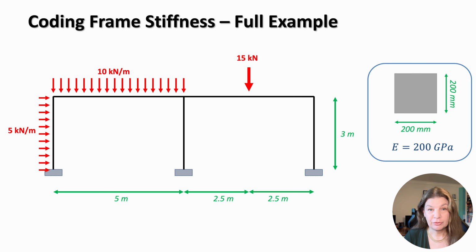The key point about this frame is that it is statically indeterminate. Equilibrium alone is not enough to determine the internal forces. We need compatibility. In fact, this is a 6-fold indeterminate structure, meaning that there are 6 additional relationships required beyond simple equilibrium. It's exactly the type of problem where the stiffness method is most effective, because it naturally incorporates both equilibrium and compatibility through the displacement formulation. By implementing it in code, we can handle the degree of indeterminacy cleanly and effectively, without the algebra becoming overwhelming.